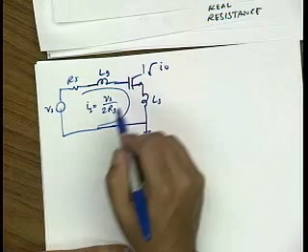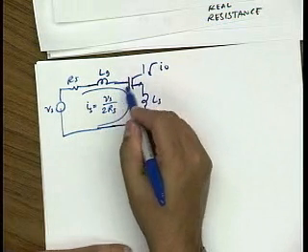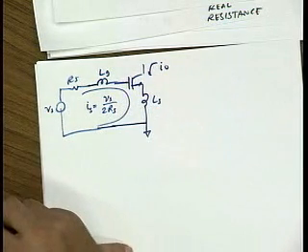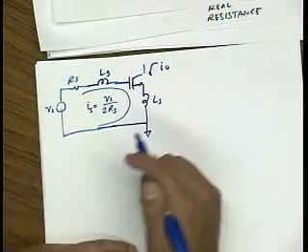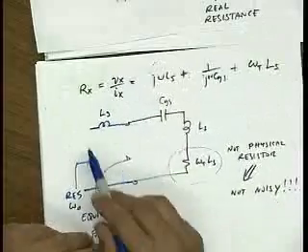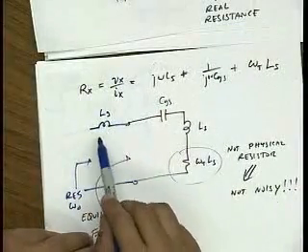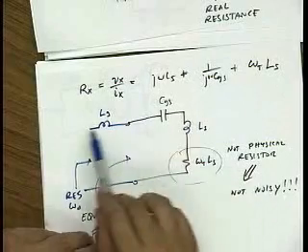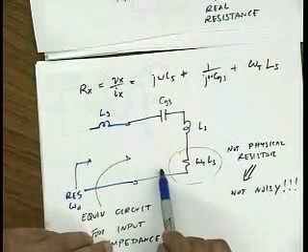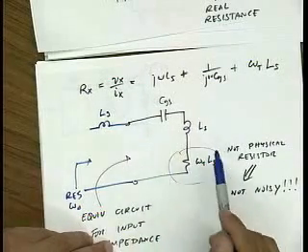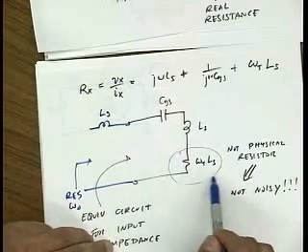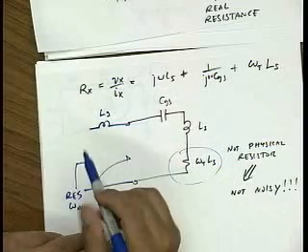Okay. Now that's approximate because there's also RG, but I'm assuming that RS is larger than RG. So the observation is that this is simply a series resonance circuit. If I hook up a voltage source here, these reactances in series cancel out and all the voltage appears across the real resistance. And the real resistance is this RS, and then the RS of the voltage source.